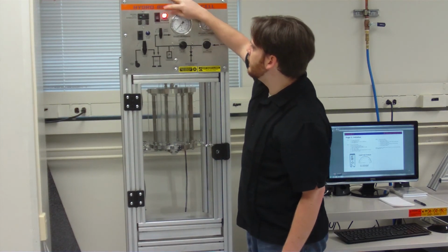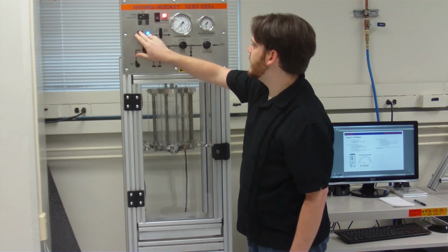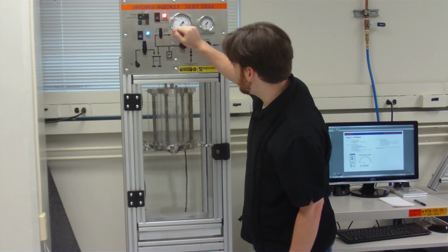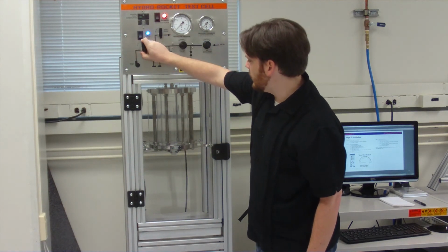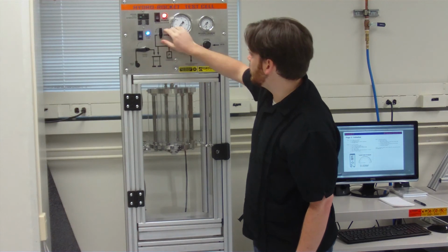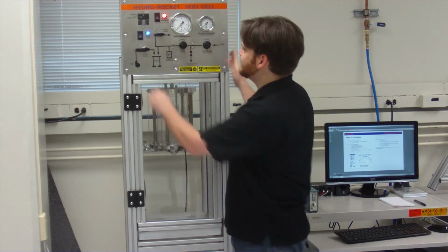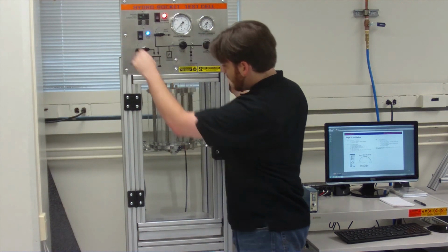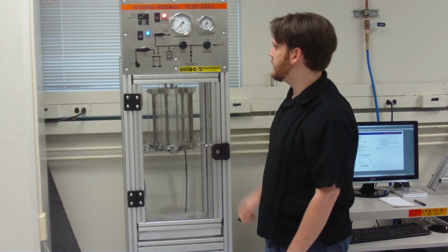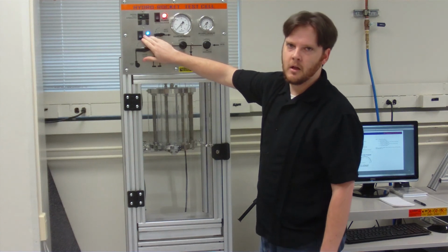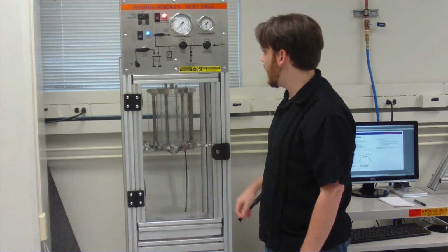The main power switch here and the water pump switch here will start the water flowing. Of course, there's this water valve that you need to open and also an air vent to keep the pressure from building up as the water gets pumped. And if the water doesn't start flowing right away, cycle it off and then on. It'll help get it started again.